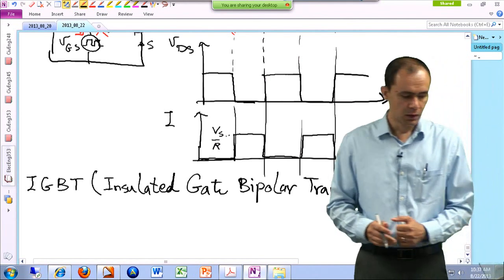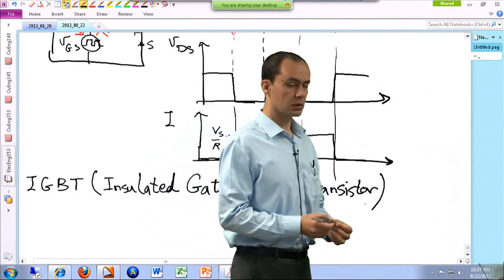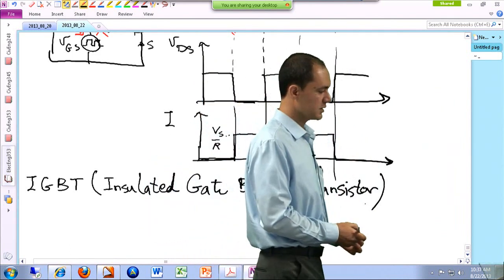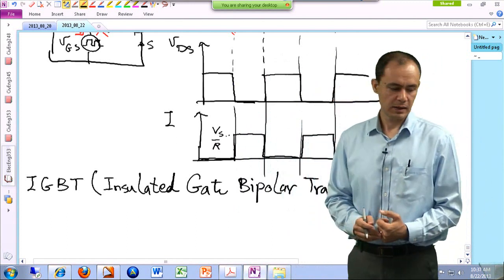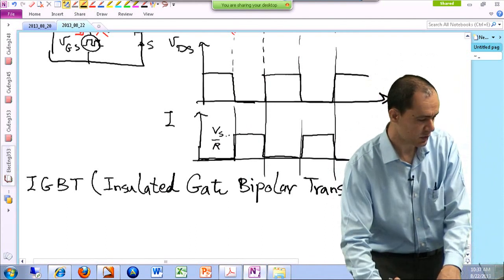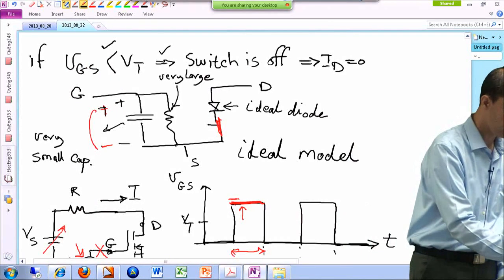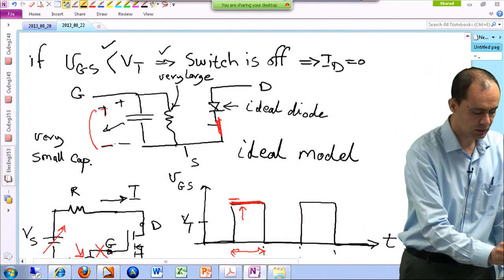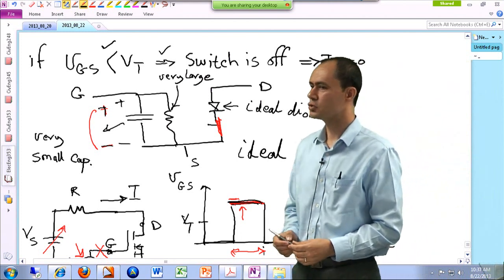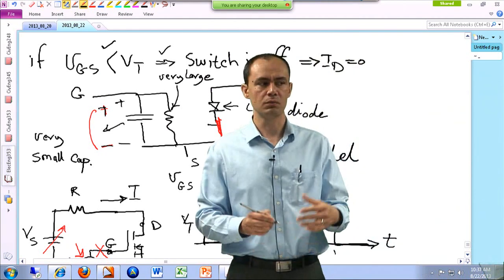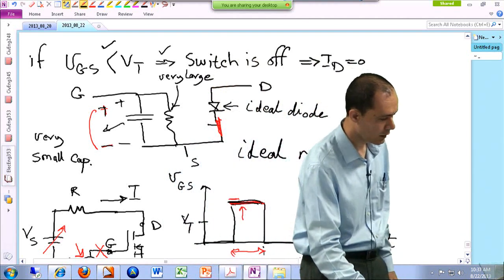Okay. So basically, they are just a basic bipolar transistor. However, the only difference is that on their gate signal, there is a MOSFET embedded in there. And as you can see, when the MOSFET is on, as soon as you charge this cap over here, even though you are maintaining your gate to source voltage, the gate part at least is not consuming any power. All you have to do is maintain the state of charge of that cap and the device is going to be on.